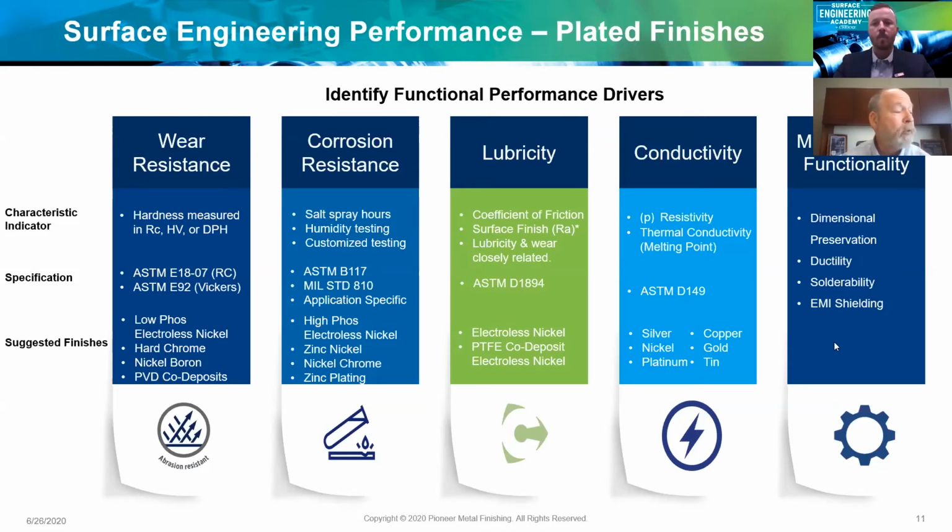When you combine lubricity and hardness, that's where you see your best wear resistance. The advent of the Electroless nickel coatings where we can add the PTFE and combine the slipperiness of the PTFE with the hardness of the Electroless nickel provides a very good coating.